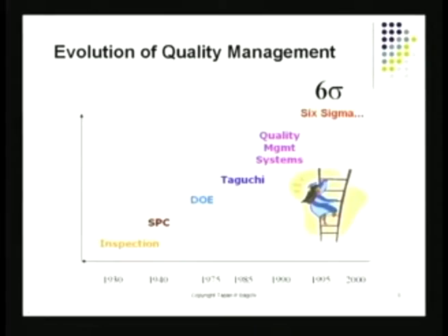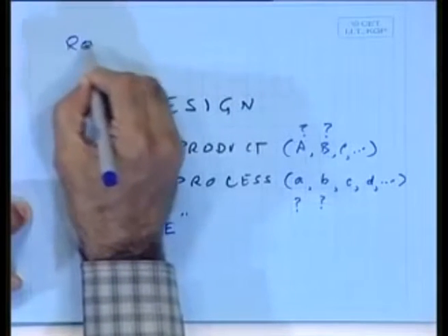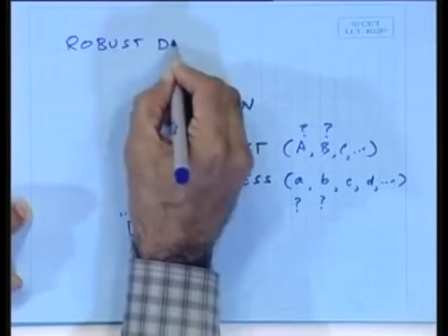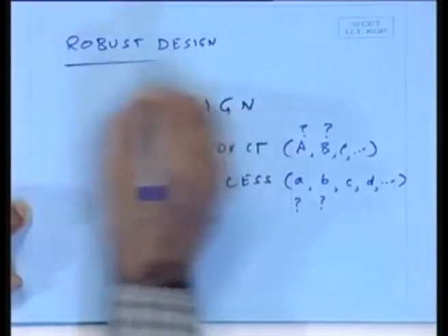And he came up with some very special designs. One of the kinds of designs he came up with is called robust design. I'll give you an example of robust design. As we go into it, you'll find these are very special designs and they hold on to their performance even if the environment becomes hostile. Even if there is dust, humidity, high temperature, low temperature, vibration and so forth, or component qualities are not that good, even then a robust design will retain its performance. That's a very special type of design, and Taguchi was the father of that kind of creation.